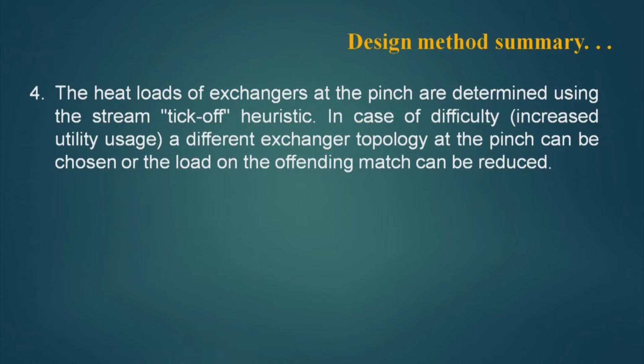The heat load of exchangers at the pinch are determined using the stream tick-off heuristic. This stream tick-off heuristic is based on the number of units target, and if we follow the tick-off heuristic, which has been explained earlier, then the number of units will be less, and if we do not obey this tick-off heuristic, the number of units may be more, or it will be more in most of the cases.